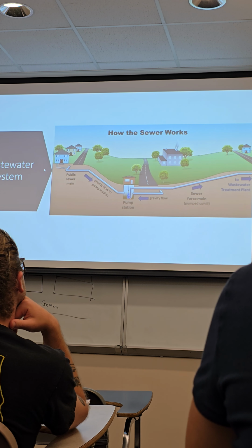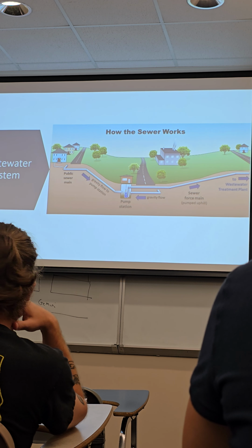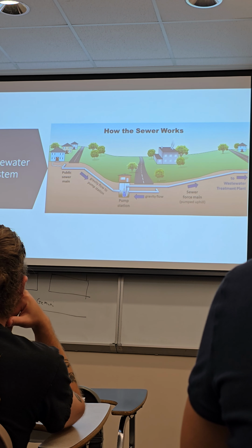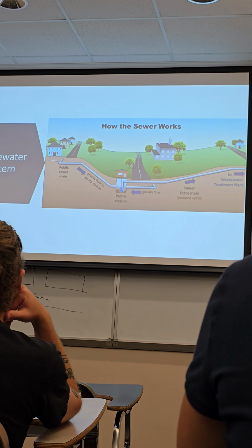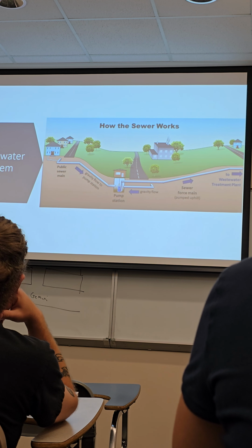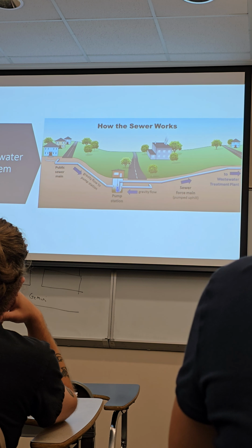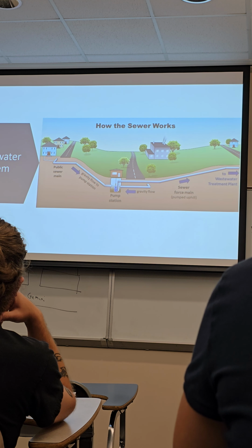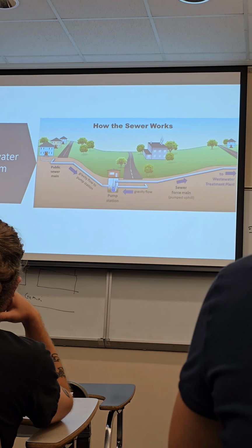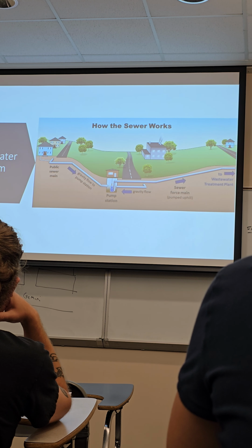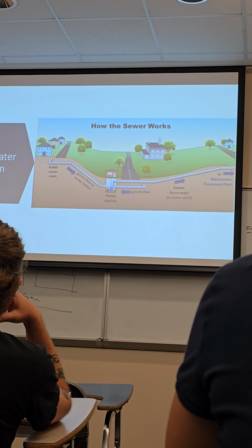But one of the challenges in Florida is that it's pretty flat, right? So there's a certain amount of gravity flow you can have before you start getting pretty deep with your pipe. The pipe's just getting deeper and deeper and deeper, but at some point I can't really go any deeper. There's a practical limit to the depth of the pipe. So what do?